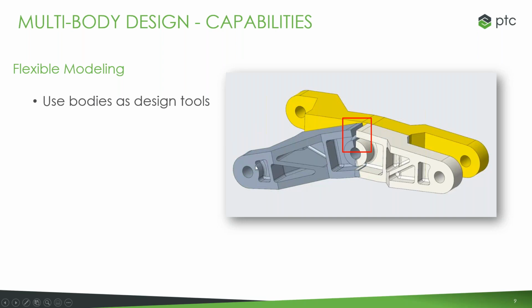You don't have to now make all of these things on an angle. It's a very effective way to do it, even if it's just for concept design, which is where a lot of times we see flexible modeling being used. Hey, what if I wanted to change the angle that this sits? Great, split it, turn it. Not a lot of parametric definition that you need to do to see that change, and then decide if you like that method and you want to go forward.